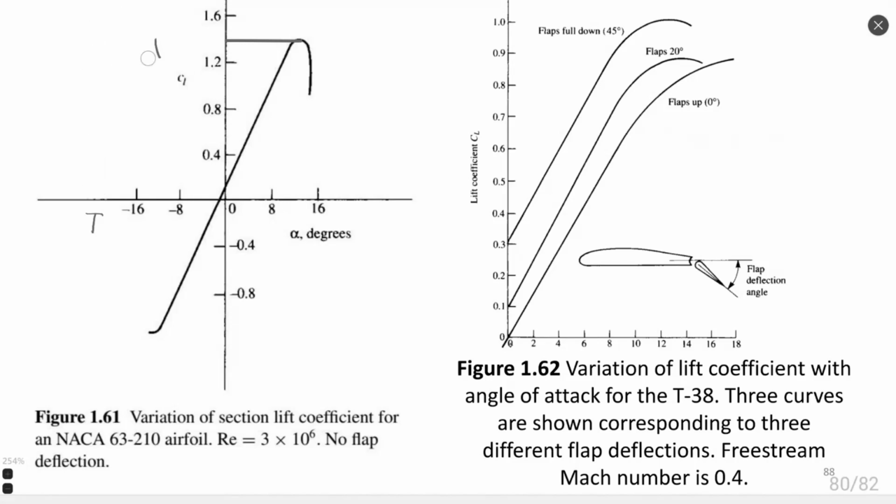Typical values of lift coefficient are 1.2 to 1.5. There are more performant airfoils, as I said. There are airfoils which have a lift coefficient of 2. It's higher, right? For example, our competition team, Mammoets, use an airfoil which has lift coefficient 2. It means that you have very high lift created by size. It's very good from one point of view.